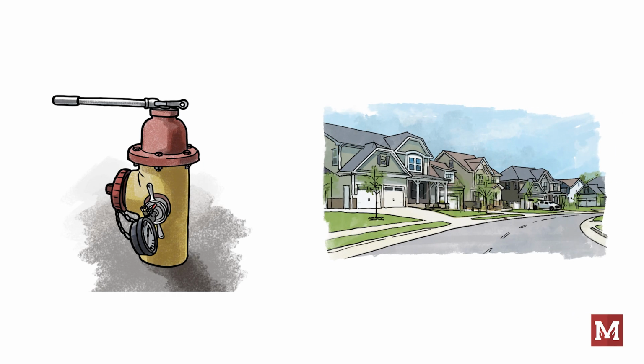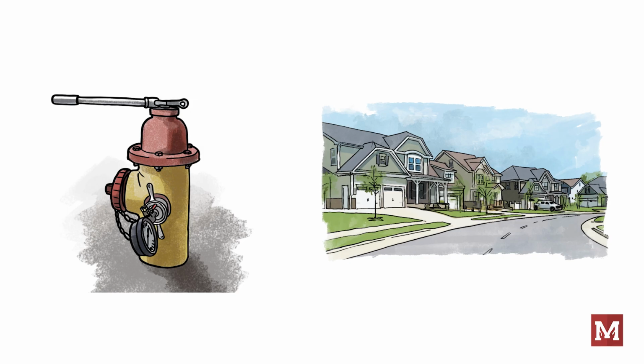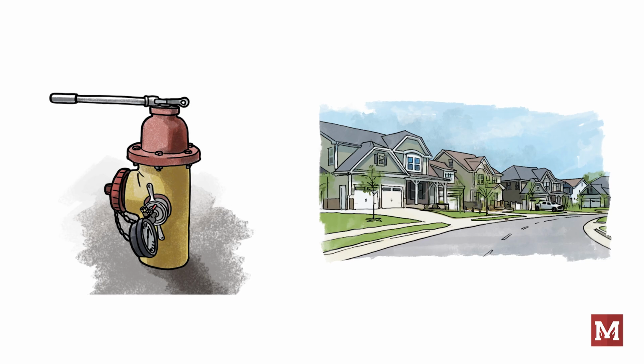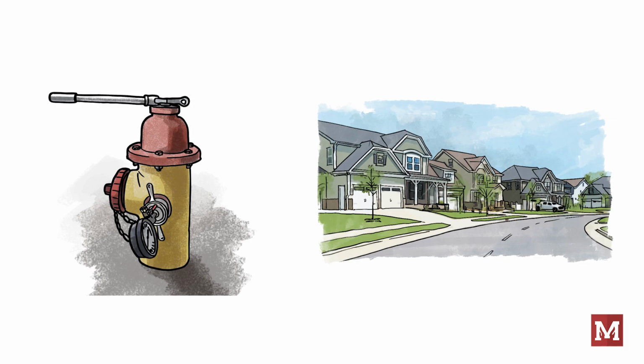These are going to be a couple hundred very high-end custom homes in a very exclusive community. We have to protect the community's gatehouse/community center. The water system hasn't even been built yet, so there are no fire hydrants for us to test and obtain the fire flow data. The utility contractor designing and installing the underground infrastructure and water treatment plant have said that we can expect a static pressure of between 35 and 87 psi.